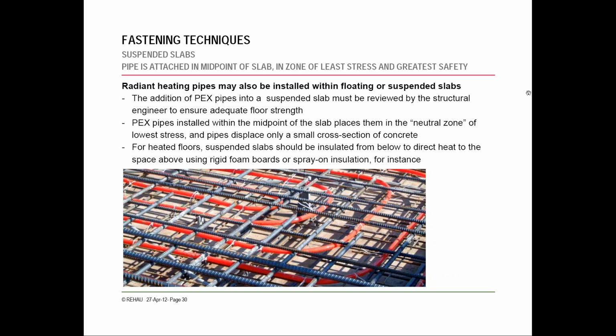All right, so just real quick, touching on suspended slabs or floating slabs, we do get a lot of questions as far as how the tube is affecting the structural integrity of the slab, especially if it's load-bearing and suspended. It's something you do want to make the structural engineer aware of, obviously, that you're going to be running tube through it. But as you can see from this picture, it's basically the diameter of one piece of rebar. So as long as they're accounting for it, it's not causing a major change to your design at all. Once you make the structural engineers aware of it, it usually will not change your design at all. But it is something you want to make sure they're aware of, obviously.